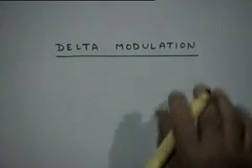Now, one of the techniques which is extremely simple to implement to do this is what is called delta modulation, right? So it is not a modulation in the usual sense of the word, that is, you have a sinusoidal carrier and you embed your information onto the sinusoidal carrier. But yes, even in the usual sense, it is a modulation, because the carrier here, like in other pulse modulation schemes that we discuss, is a train of pulses. So in that sense, it is a modulation because you are modulating a train of pulses, right? But the modulation is simply binary in nature. The primary purpose of this modulation is representation of the analog information in digital form, right?